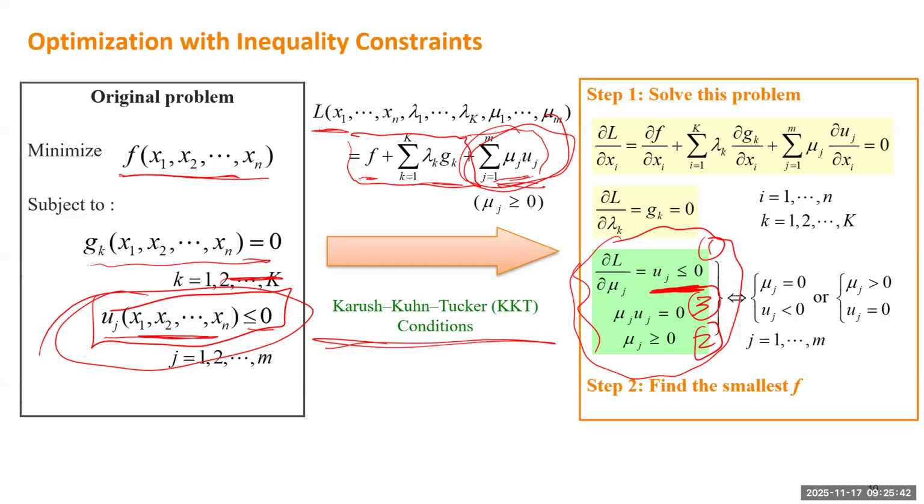Then starting from now, we just forget about the original formulation. Let's go ahead and solve everything in this box. The yellow items come from setting the gradient vector of the L function to 0, and the green part comes from the KKT conditions. So if you want to solve a very high-dimensional problem, like dispatching tens of thousands of generators, you definitely want to program your code or your solver based on the yellow and green expressions.